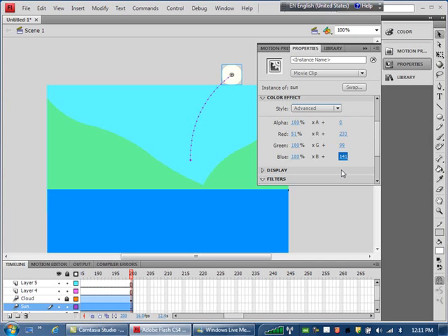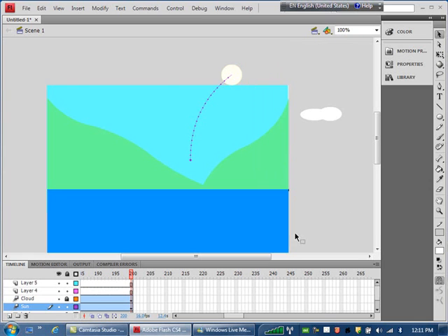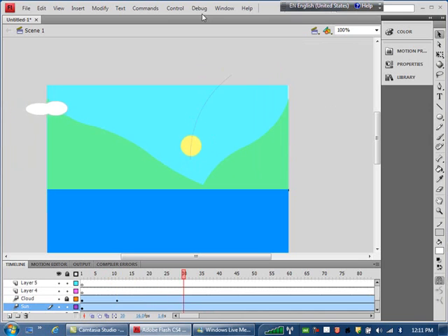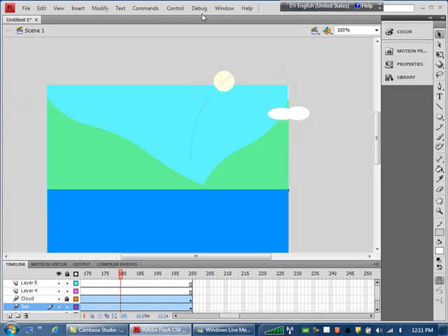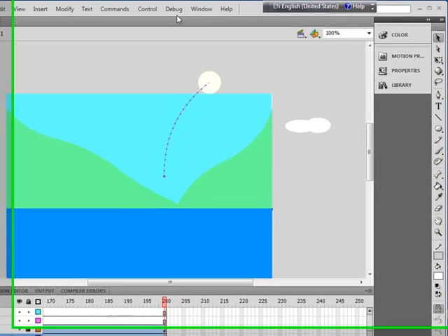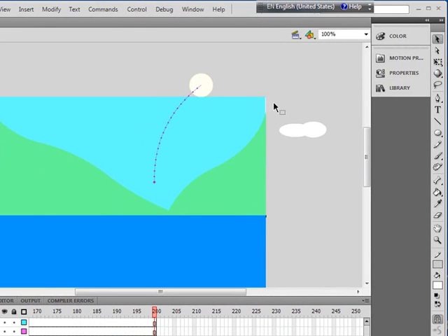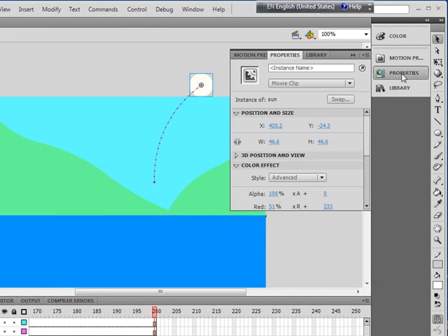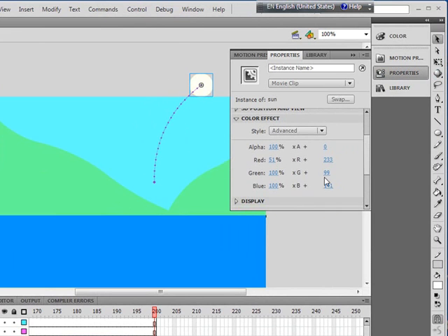All right. So now let's test it and see how it's gonna happen. What's gonna happen? It starts yellow, and it should be turning brighter as it gets higher. Clear? Do you see that? The effects? So how do you do it? You go to the end, for example, and then you click on the property, select color advanced, and then you can change the color shape.